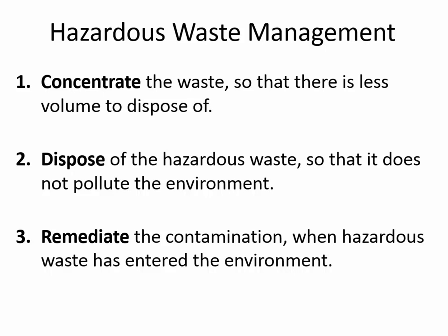And in the homework you have a problem where I ask you to do a mass balance, and what you should do is think about the black box concept, where there's things going in, things coming out, and they can go out of the so-called black box in multiple locations. It may be a sludge where some of it goes. It may be what they call drag. And drag is when, for example, if a part is submerged into a chemical, when you take it out of the chemical, it still has a little bit of the liquid on the outside of the part. So that's in the homework what it means by drag.